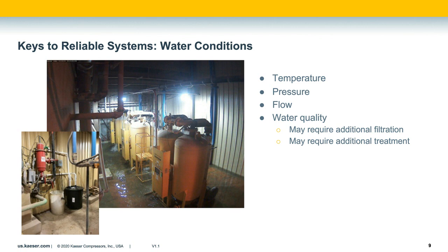Poor water quality can also foul your coolers and cause them to clog over time. Some coolers can be cleaned externally and some cannot. So be aware of that before you make your purchase and plan for a worst case scenario.